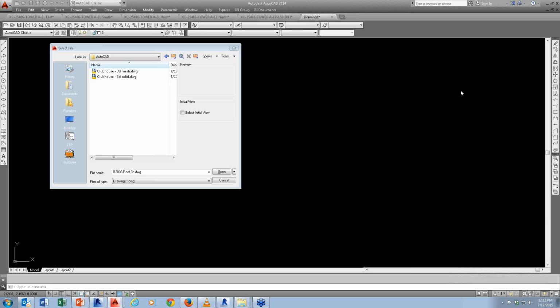Can it easily fix blemishes and fake display? What it means is that in a 3D model, sometimes you will see the objects are everywhere, right? With Revit, you can actually manipulate it and make it look like you can hide that stuff. Whereas in AutoCAD, it's what you see is what you get, and it's very difficult to hide stuff. You have to go in and create layers, put that object in that layer, and then that's how you turn them off.